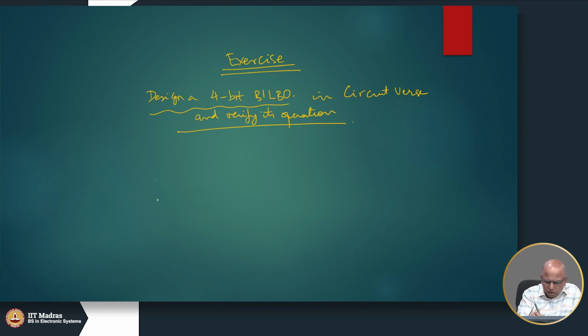So first let us understand how we can convert. Let us say this is a 4-bit register and we have taken 4 flip-flops. See, if you are doing parallel in, parallel out, then the D input comes from P0, P1, P2, P3. And if you are doing serial in, serial out, then this guy has to come from Q0. So we can multiplex these two guys.